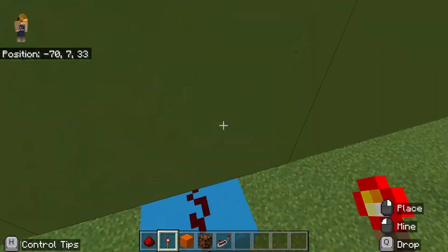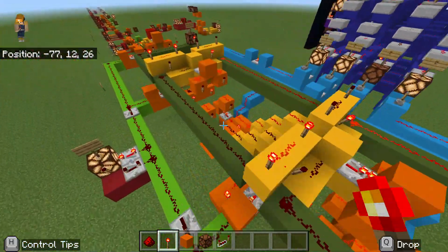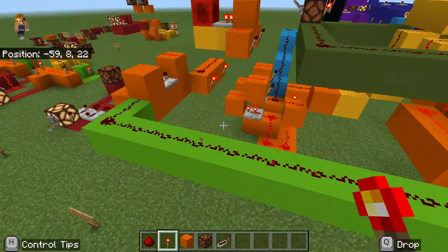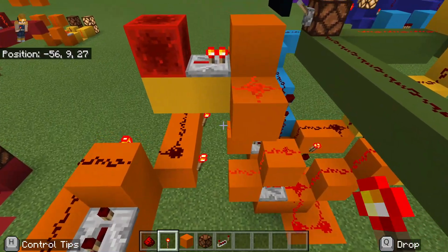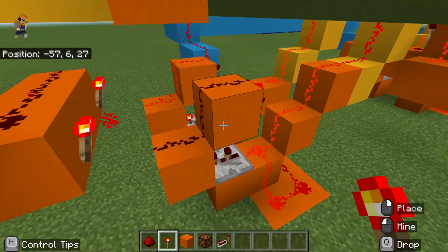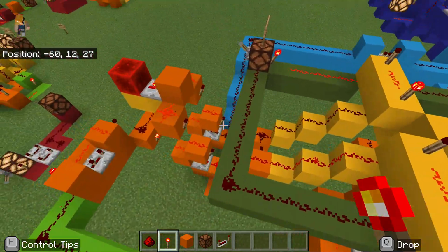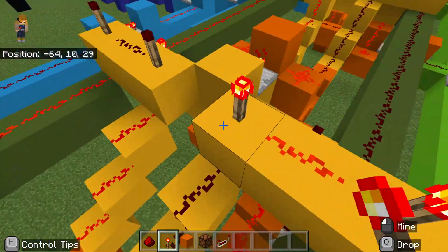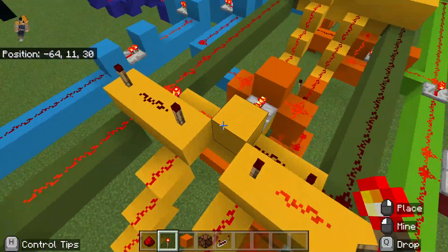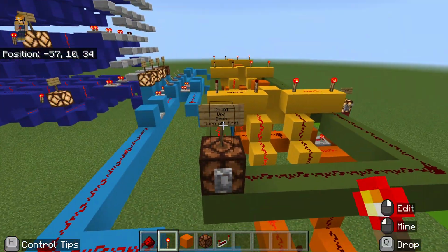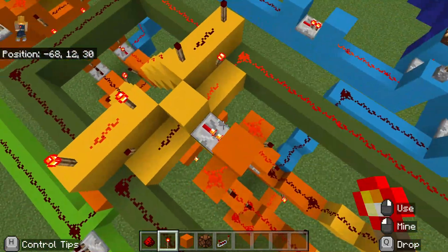And then we're taking our Q output as the left side here. That's going into those 4 outputs there. Our clock goes into a monostable circuit first, just so it's a pulse, and that goes on to our outputs, and then here we have an option for counting up or down.